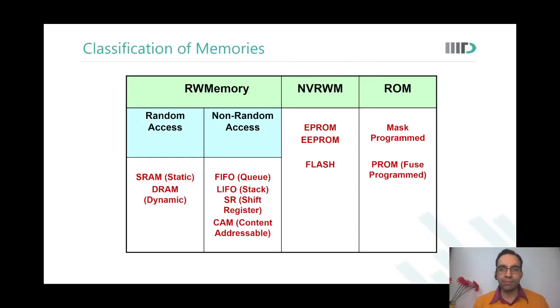Any questions about that? In this, we are trying to go the reverse way from the content to the address. But for the content matching also, there would be some kind of reading from a particular location that matches, wouldn't there? Yeah. In a typical SRAM, you will have to read, compare and then say whether it's a match or not. If it's a 100 word RAM, you will have to do 100 cycles to do even one comparison. Am I right?